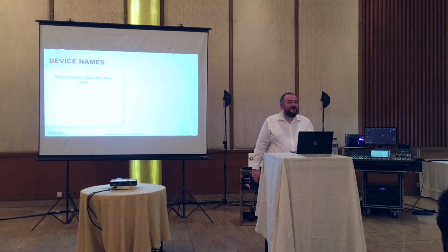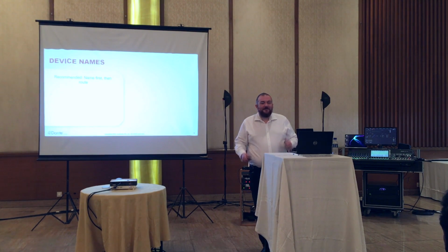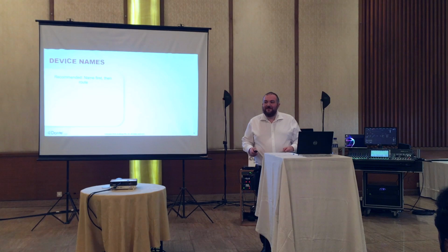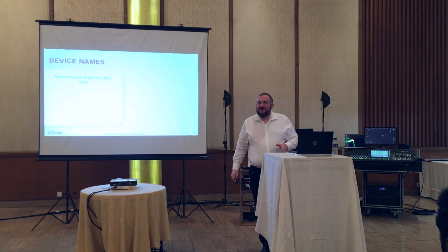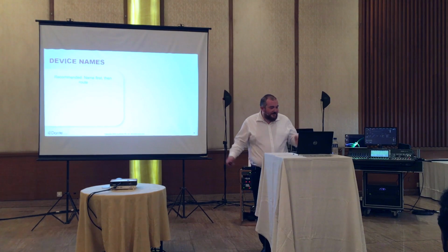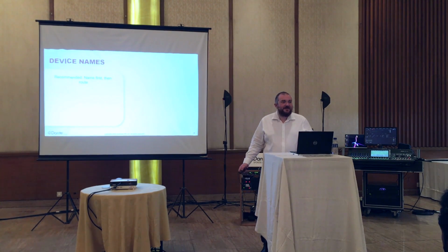And you're not going to know which each amplifier is. And then you're going to have to go through some difficult way of unplugging it, working out which amplifier is which. So please just plug one thing in at a time and name it, then plug in the next thing, just like you would do with electrical tape and a pen on an analog system. Otherwise things get too confused. Okay? Yes, all right, I don't do that every time and I regret it every time I don't do it.